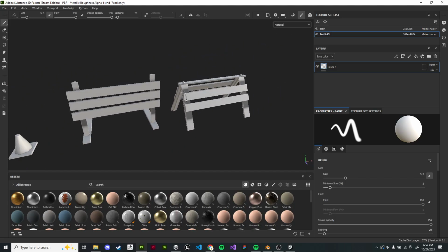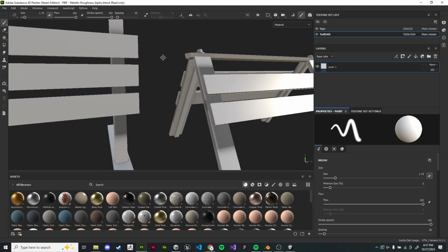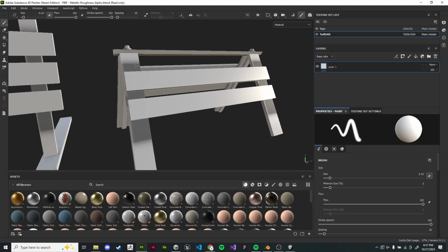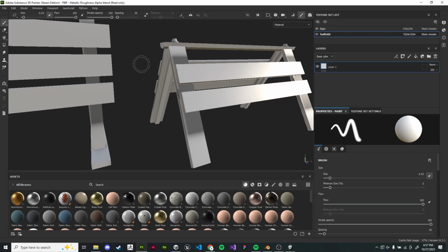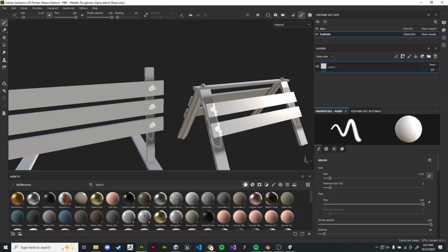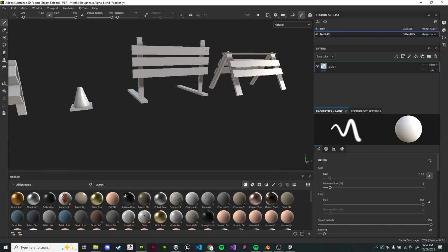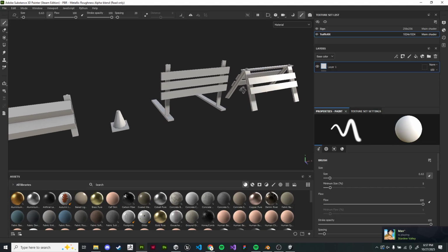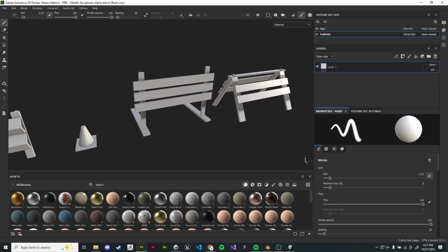When we have these overlapping UVs, what happens is it's going to bake the ambient occlusion, for example, from this object between these two. But then that means that when we reuse this object, we have that same ambient occlusion. So it's getting the ambient occlusion from here as well as from here, which is why we're just getting this black strip across that entire length. So the first thing I'm going to do is just get rid of the ambient occlusion. It's the only one that has problems when we do this kind of thing. There are easy ways around it as well, but we just don't need it straight up.